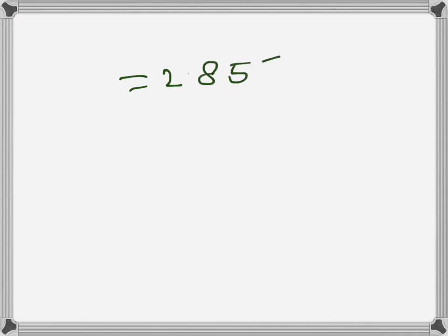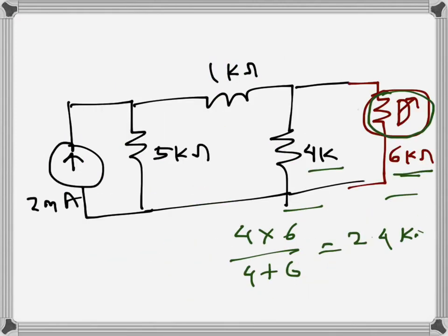So much less than the actual voltage drop, which is 4 volts, and that is happening because the voltmeter has a comparable resistance, comparable with the resistance across which it's trying to measure the voltage drop.